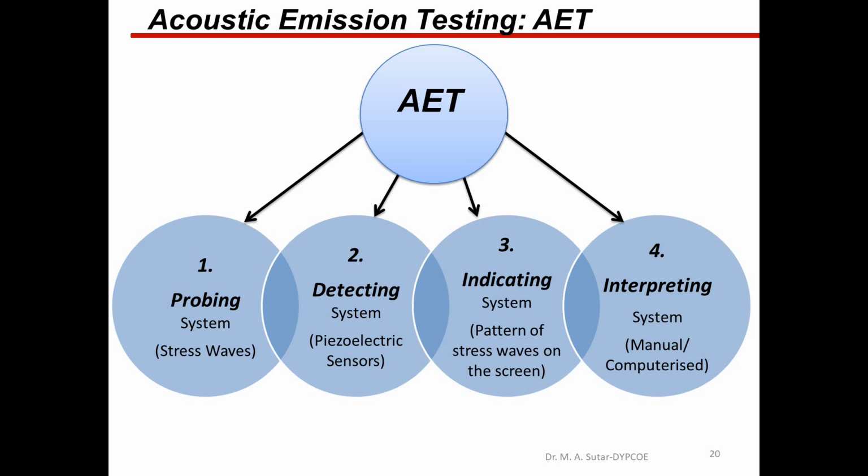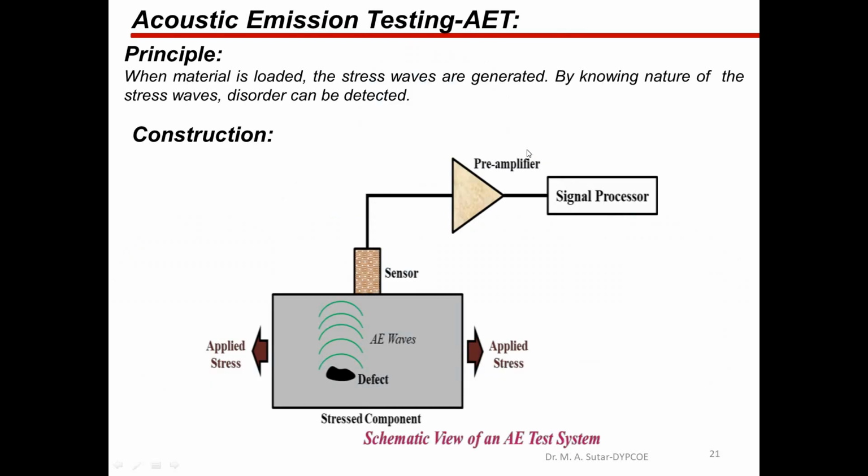Indicating is in the form of a pattern which will be observed on the screen, and interpretation can be done either manually or with the help of a computer. The principle behind acoustic emission testing is that when material is loaded, stress waves are generated, and just by knowing the nature of the stress waves, disorders can be identified.